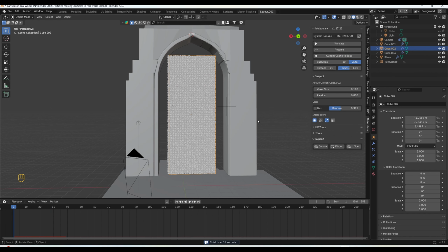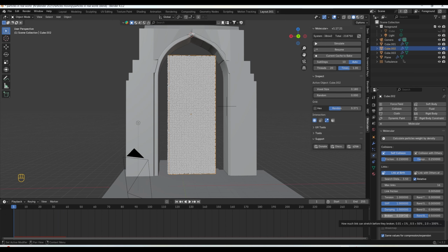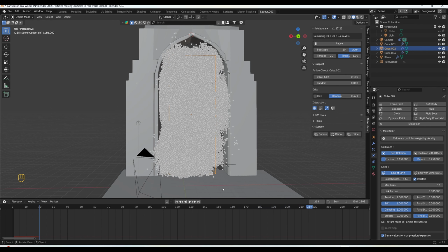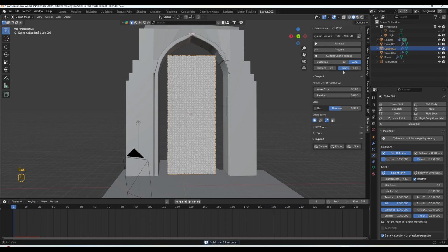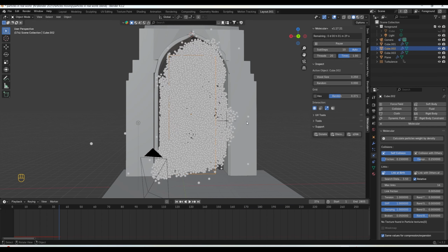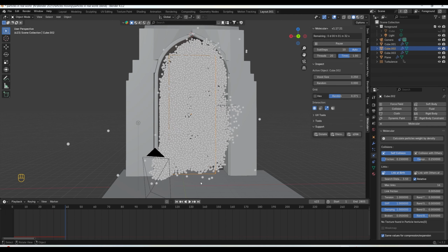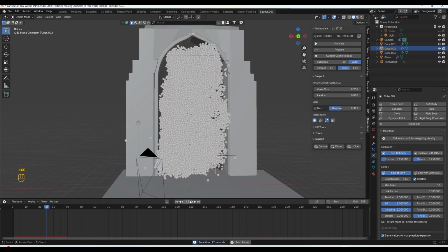that particle. What I will do now, I will select this, go to the physics properties, go to the broken and just make it 0.5, maybe 5. So it's too low. Press ESC. I will select this once again, and in the voxel size I will just make it like 2.5. So you can see this is looking nice. Let me play once again.